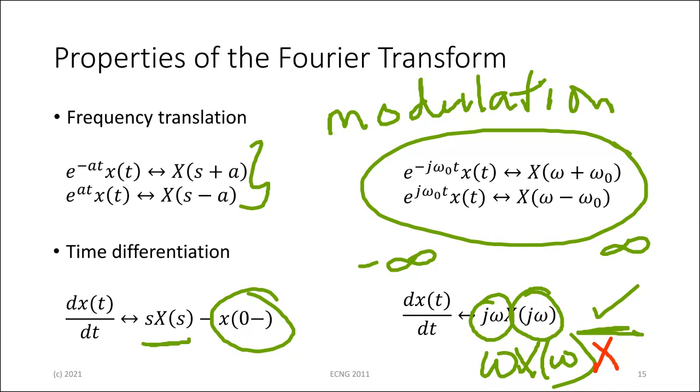So the first major difference, of course, is that the Fourier transform doesn't handle initial conditions, because it is assuming that everything has been going on from t equal minus infinity to infinity, or for more practical terms, that the thing has been on and the signals have been existing for a very long time.